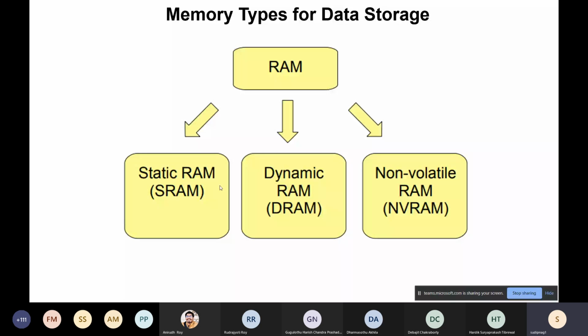Only it will take some energy and time to do that. But NVRAM is more like flash memories, while also having some characteristics of EEPROM that we discussed in the previous slide. As I said, EEPROM is typically byte accessible, whereas flash is page or segment accessible. That means a group of memory should be erased for flash, but reading from flash could be done byte by byte.